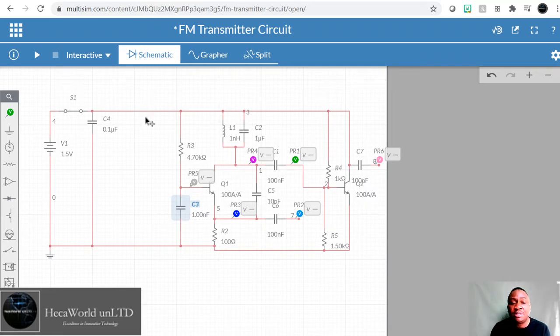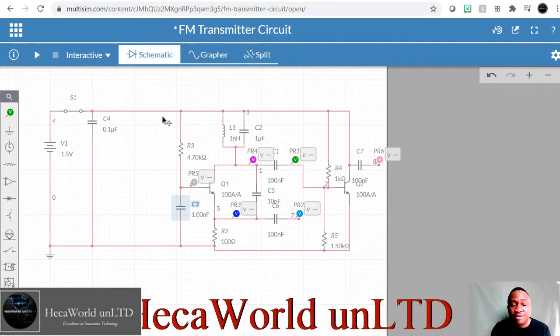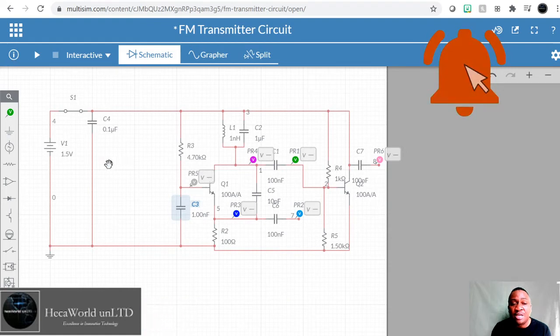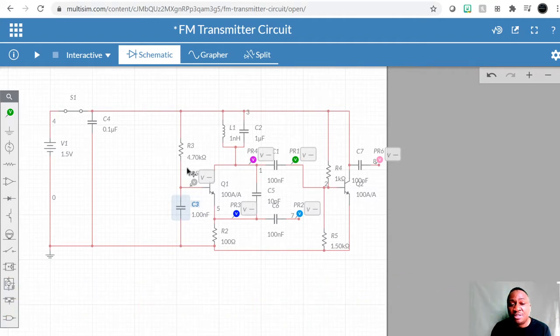Include a voltage regulator and then increase your voltage source. Let's say you have 4.5 volts here and you have a 1.5 volt voltage regulator. You can build this using a Zener diode, right? So if you have a 1.5 volt regulator connected to this circuit, then you are sure that as long as the input voltage is greater than or equal to the regulator voltage, this circuit will function stably.